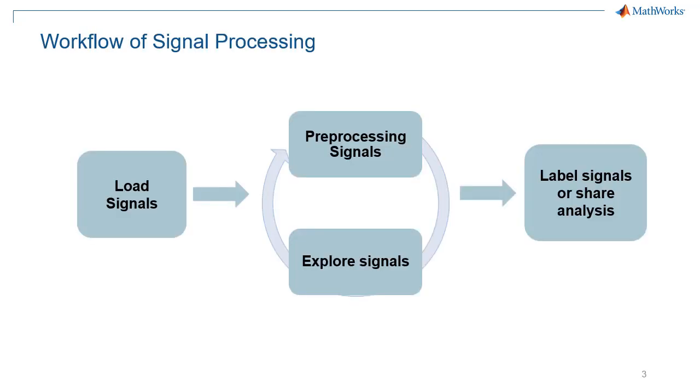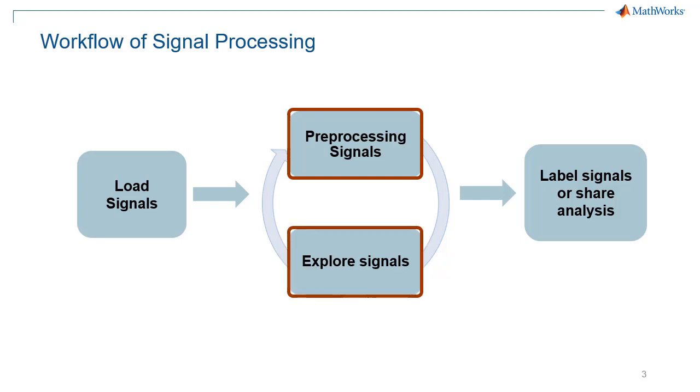Signal processing involves all aspects of our life, such as biomedicine, communication electronics, computer vision, and so on. Usually, we need to load or import the signal before we do signal processing. MATLAB supports signals represented by vectors, matrices, timetables, and time series. Then, the signal is pre-processed and is observed and analyzed by time-frequency analysis. Generally, the pre-processing includes filtering, smoothing, resampling, detrending, and calculating envelope.